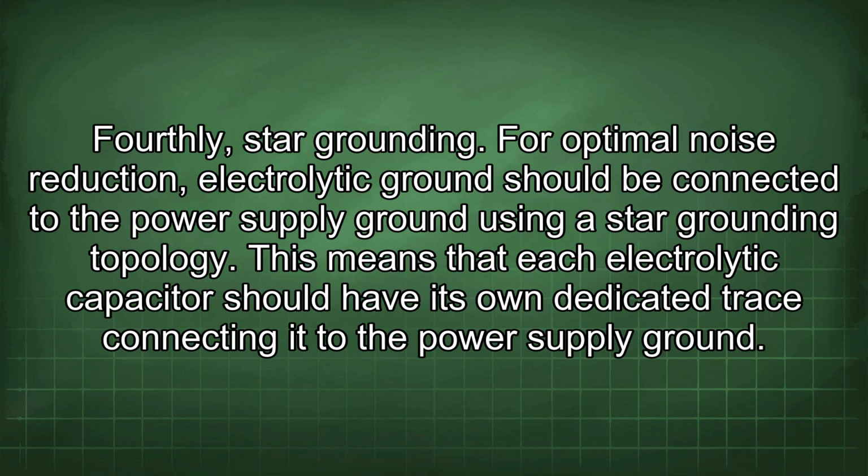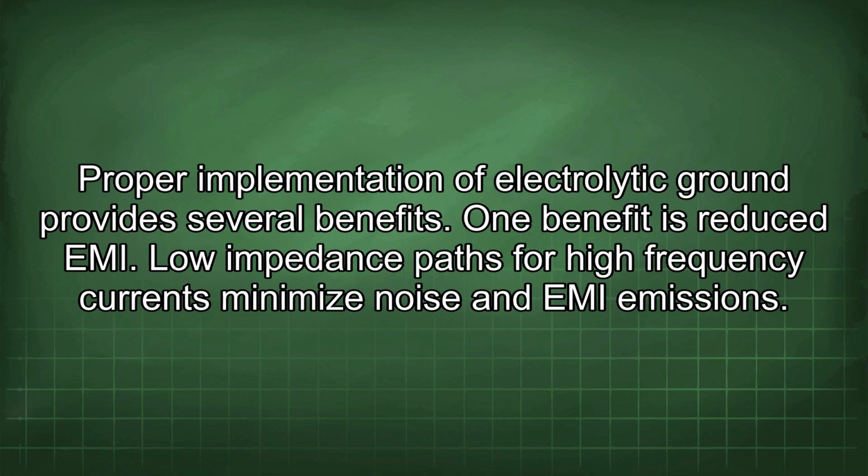Fourthly, star grounding. For optimal noise reduction, electrolytic ground should be connected to the power supply ground using a star grounding topology. This means that each electrolytic capacitor should have its own dedicated trace connecting it to the power supply ground. Proper implementation of electrolytic ground provides several benefits.